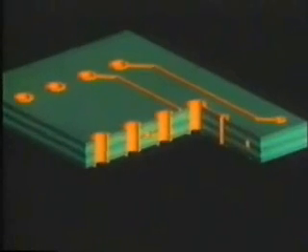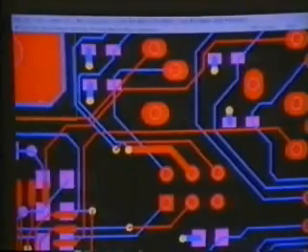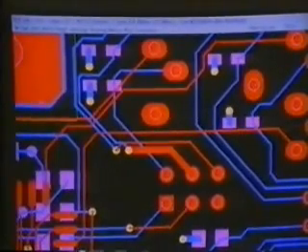In this cross-section of the circuit board, we see these transmission lines are routed through several different layers using channels called vias. The materials surrounding the transmission lines and the line's dimensions contribute to capacitance, resistance, and inductance, which affect the signal's performance.